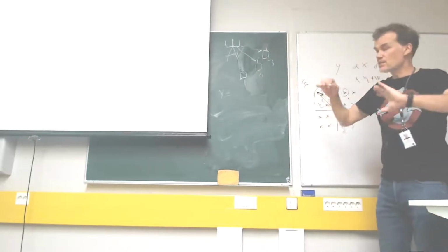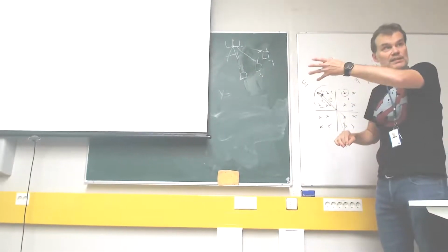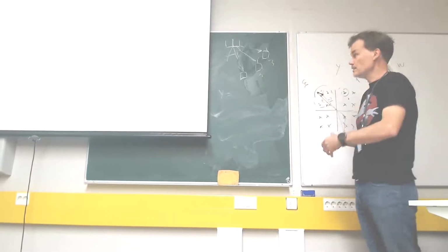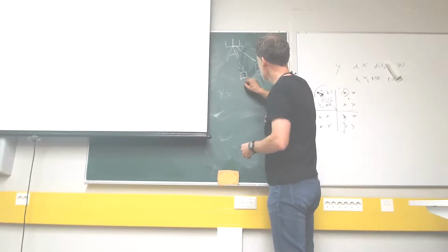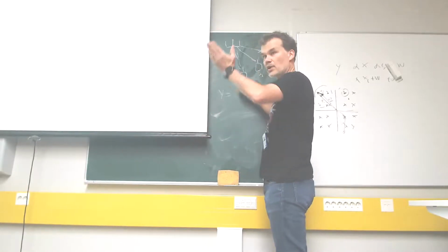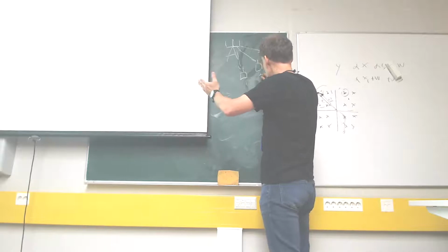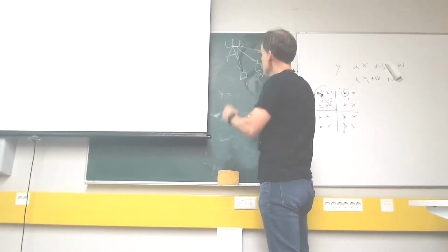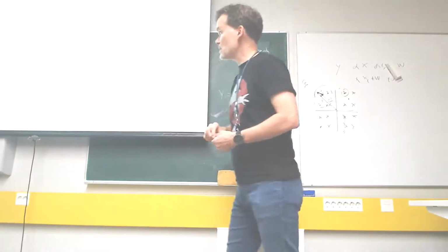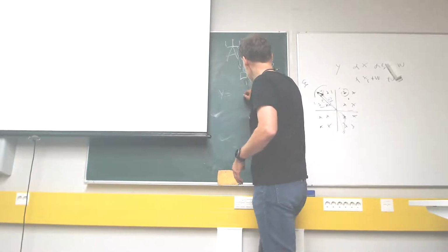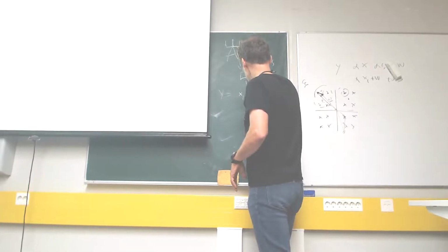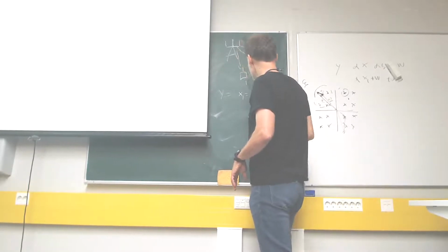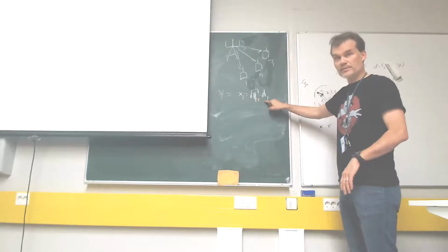Okay, downlink channels, but let's consider now the dual uplink that we already discussed earlier for the linear case. Right, the dual uplink model for this is that the user 1 is transmitting in dual uplink with power Q1, and the others with power Q2, Q3. And then we are interested in decoding a certain message, right? The X of user 1 is Q1 D1, right? The power allocation at the symbol.